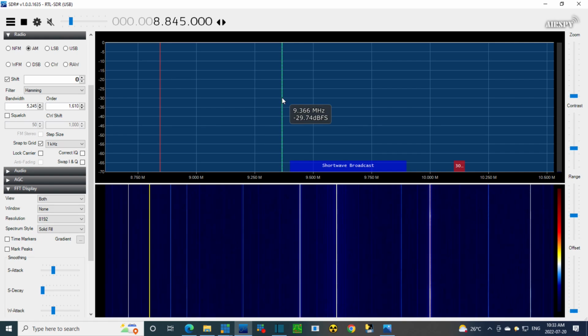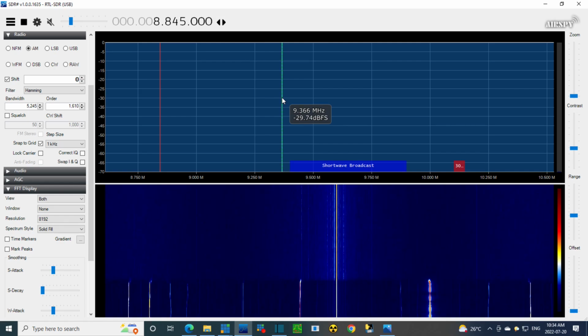Because with that at 10 megahertz, the radio dial should be pointing at 9. Oh, it's pretty close on the dial. 9.55, wouldn't it be? Okay. We're going to go on to the next one. So this one, our local oscillator seems fine. Next one. Okay, now we're at 11 megahertz, and on the dial, doggone it, there's nothing really simple here mathematically, so I'll pick 11.75 arithmetically, and we'll jump up to 11.